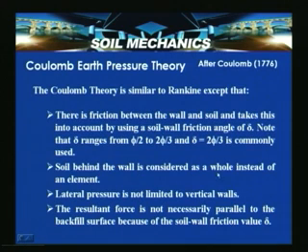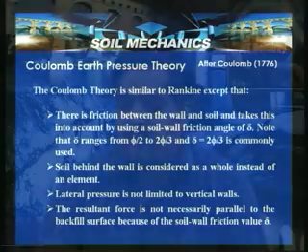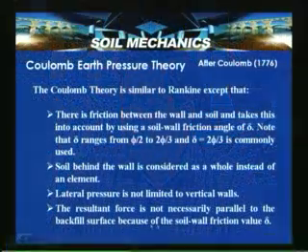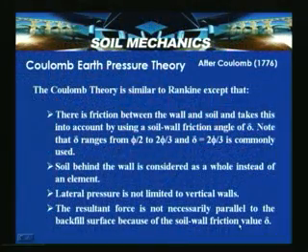Then the soil behind the wall is considered as a whole instead of an element. And lateral pressure is not limited to vertical walls. You can have a wall with any inclination, and the backfill surface can have a slope, and need not necessarily be horizontal. The resultant force is not necessarily parallel to the backfill surface because of the soil-wall friction value delta.